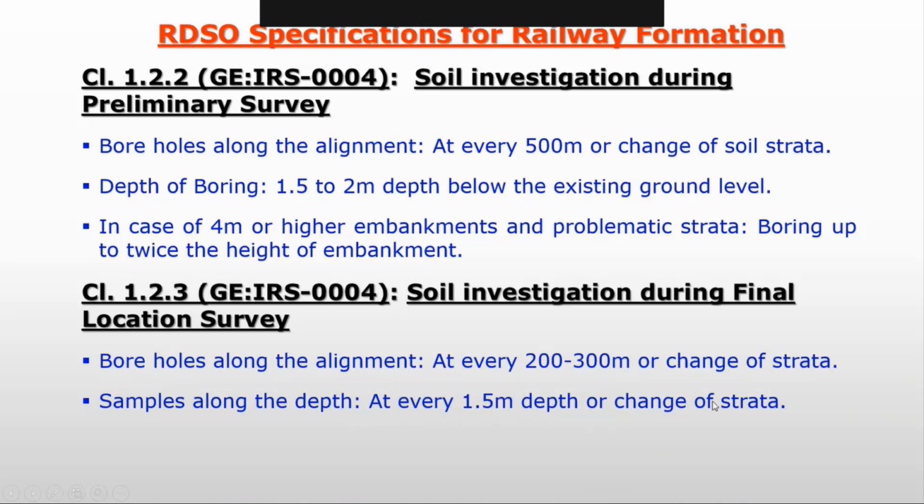If you find that up to 1.5 meters the soil is very weak, then you may have to go deeper, to know how deep that location is, so that you take precautionary measures to strengthen the subsoil. Subsoil strengthening is a completely different subject, but has been mentioned in this report.